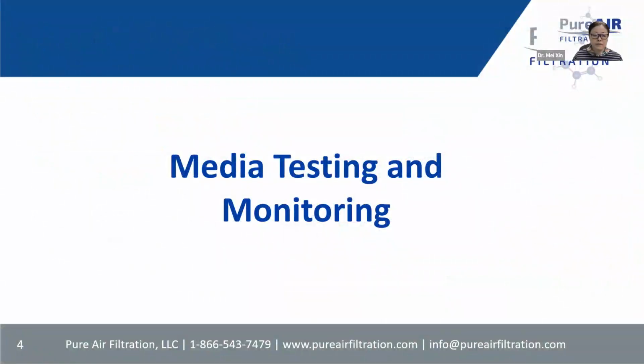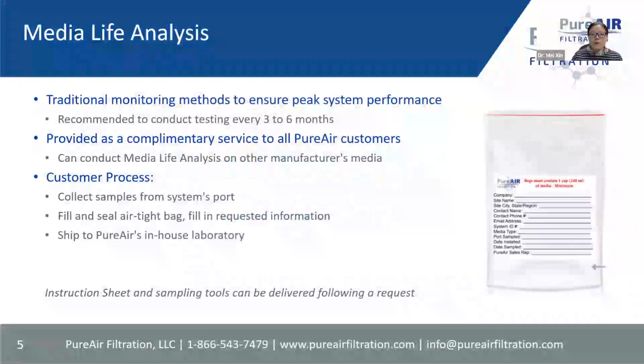So for media testing and monitoring, once a filtration system is operational, media samples should be collected every 3 to 6 months and analyzed to project the remaining life. This can prevent unplanned system downtime, exceeding control specs, or premature media replacement.